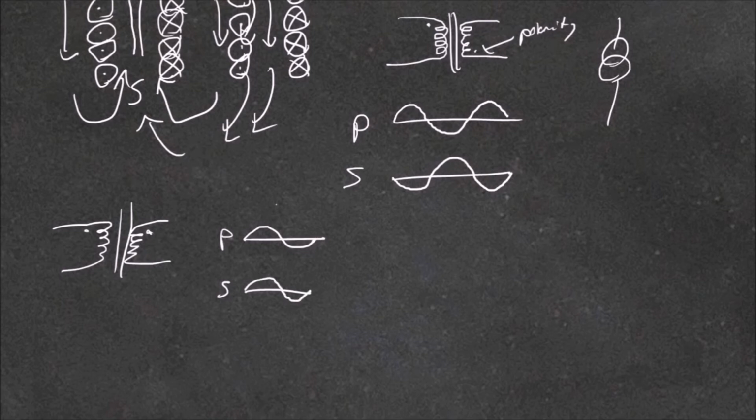As a final note, I'd like to mention some of the more practical aspects. Generally, transformers which power your house or ones larger than that would have its iron core and windings placed inside insulating oil. These are generally known as oil-filled. So this provides isolation to prevent arcing between different parts of the transformer. And you get arcing inside a transformer because there's a lot of different voltages. The top part of a winding is different to the bottom part of a winding.